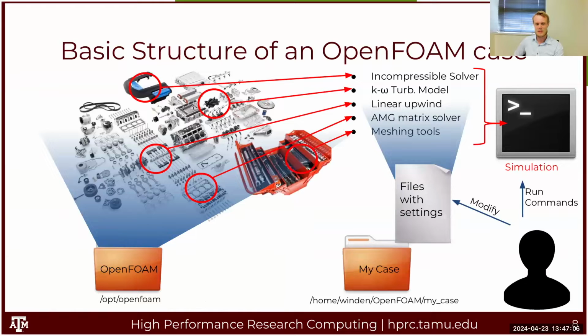So quickly, just an overview of what the structure of an OpenFOAM case is. Say you have OpenFOAM installed somewhere on your computer or on your cluster environment. That means that in that location we have all of these tools and all of these components stored. And then when you want to actually use them, you create a case somewhere in your own environment. If you're on your workstation, maybe in a home directory. If you're on the cluster, maybe in the Scratch directory, where you put little files that tell OpenFOAM what parts to pick out from this big pile of tools.